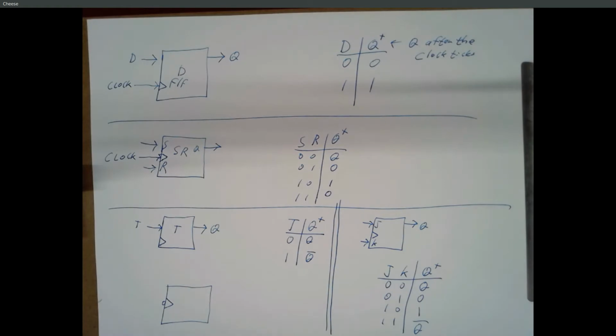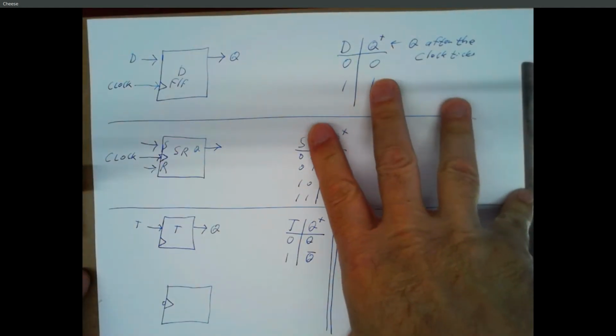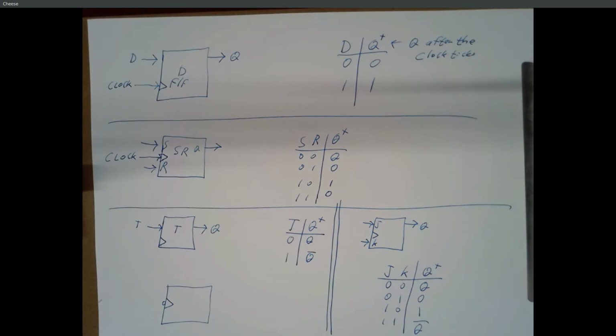But it's usually not an interesting part of, say, these state machine circuits. It's usually just coming from a line called clock. And all those homework questions that we had with these big circuits, we never even showed what was driving the clock. It was just labeled clock. Because the actual clock doesn't affect any of this, right? Your clock could come from a 555, it could come from a function generator, it could come from a push button, and it doesn't change your state diagram in the end. And you never want to put the clock in your state table, the big wide table you're making. Never have a column called clock, because then you're totally going down a different path, right?